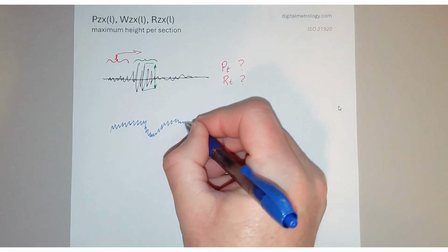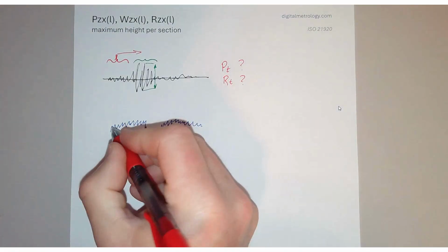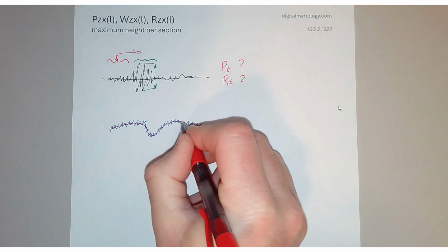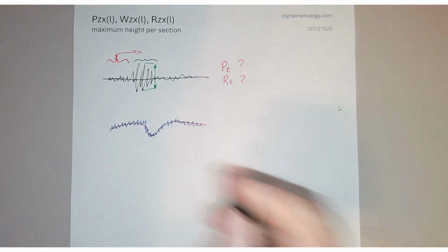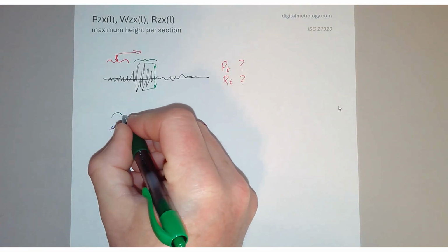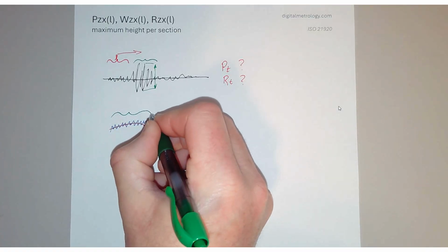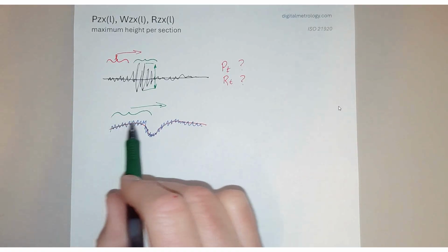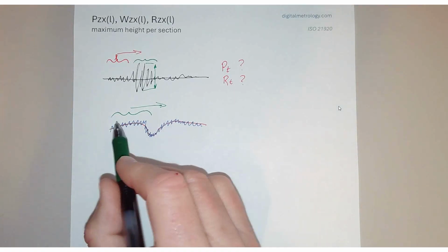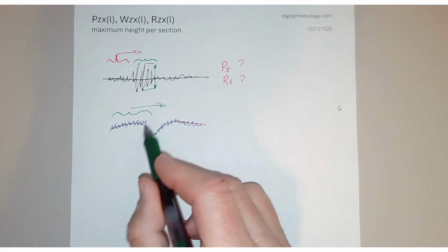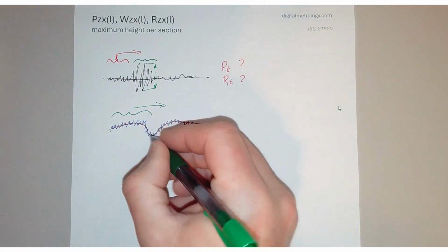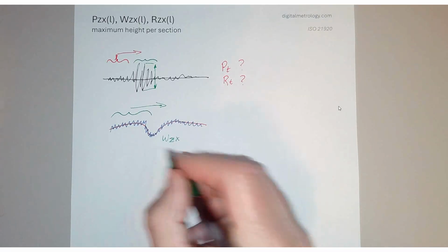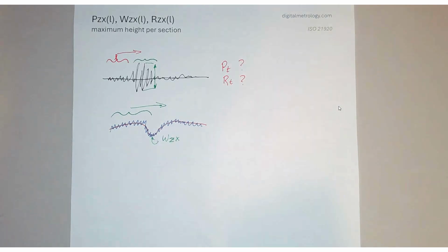For example, in the world of waviness, this surface has a dip in it. The waviness dips in this zone, and if we sweep a window of some width through this surface and we want to make sure that the surface doesn't change too much along its path, we would see that at some point there's a very large change, or a large WZX parameter that occurs in this middle zone.